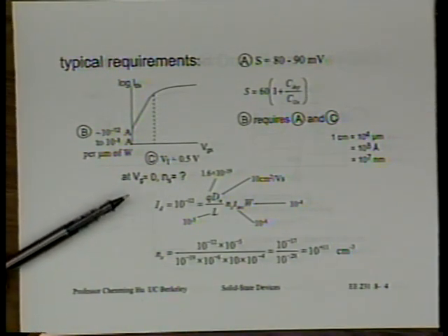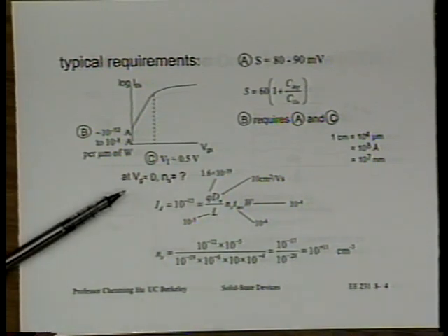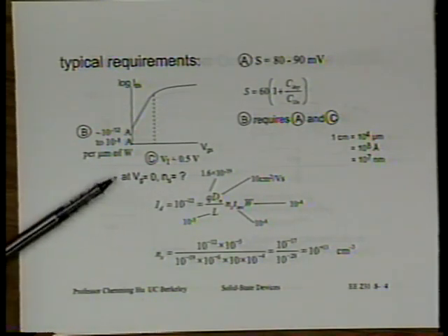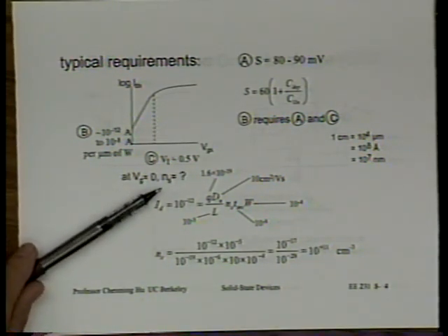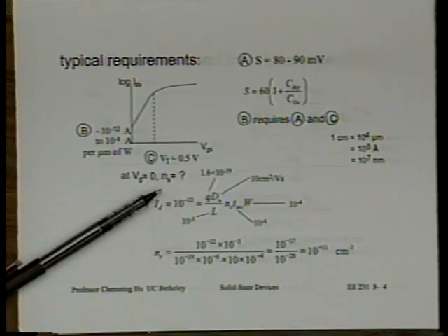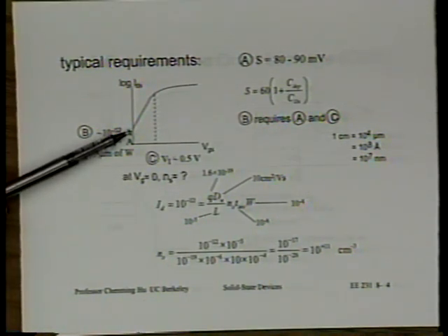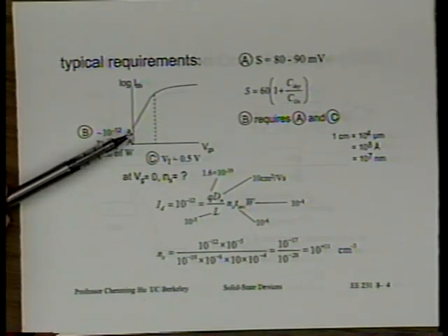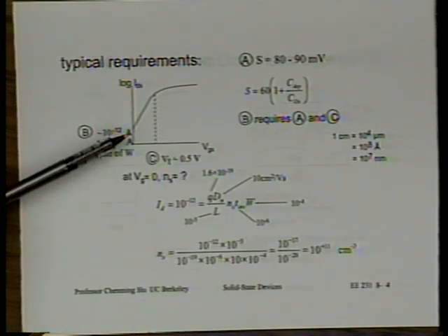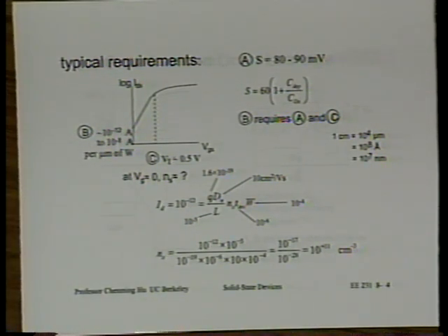All right, another kind of interesting question we can ask, given the knowledge we have: at VGS equal to 0, what kind of surface concentration are we talking about? You may not have thought about this. That is, in the so-called off state, when VGS equal to 0, are we in weak inversion? Are we below weak inversion? Is the electron concentration larger than Ni, smaller than Ni? What is the electron concentration, right? Okay, we can estimate that right now, shall we?